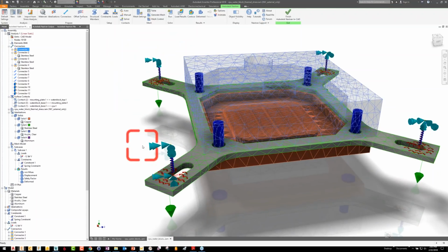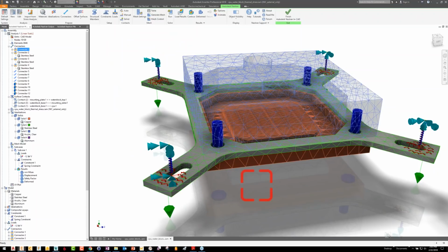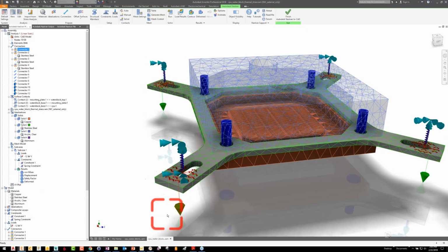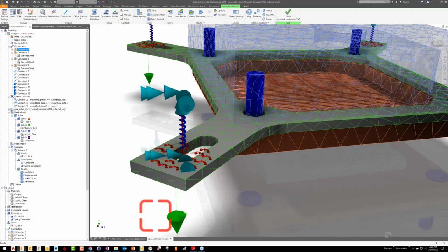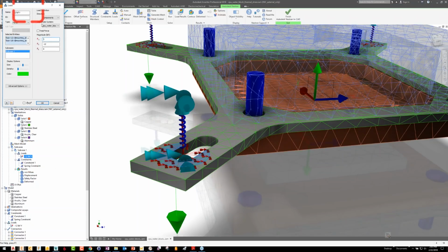So I've built in quite a bit of complexity here. I kind of had to go further than I'd really like to, but none of that stuff would have worked until all of those things were in place. So I'm at the next step now where I can try and run it and see if I like what I got. But I do need to put these forces on the top of the spring. I didn't do that yet. So I'm going to edit the force I already created and put on the pads, but I'm going to move them from the pads to the top of the springs.